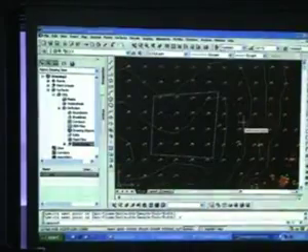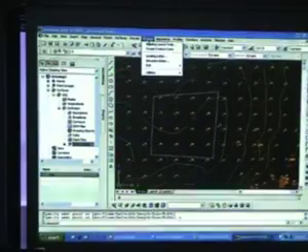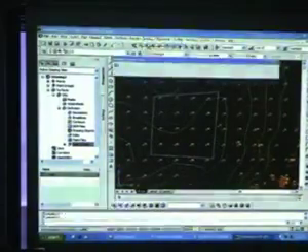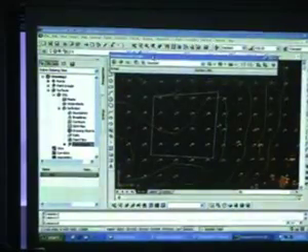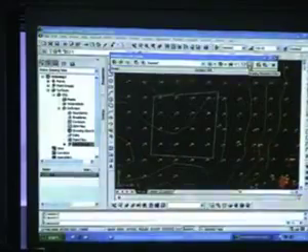But first we need to specify the elevation height, and we do that during grading. Let's go to the grading menu. Go to grading layout tools, and you have another floating menu on top of it. First we're going to modify the elevation, so we go to the grading elevation editor.